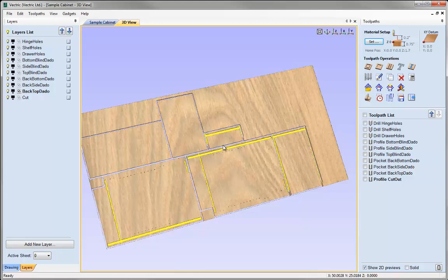And because all the toolpaths have the vector selection for picking out vectors in particular layers, all we'd need to do, if we run the nesting feature, is recalculate all the toolpaths. That would then create multiple sheets and multiple toolpaths for us to run to make multiples of this particular design, whilst saving more space on our sheet, maximising the space of our material. That, however, is all covered in a specific tutorial dedicated to nesting, and it's definitely worth a watch along